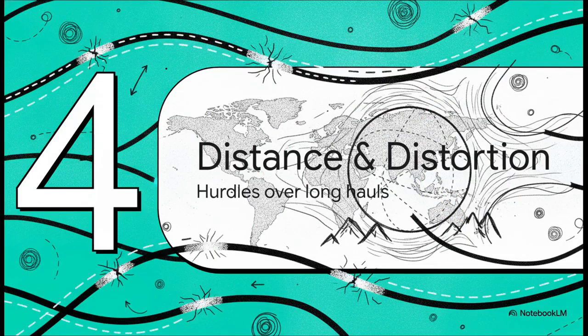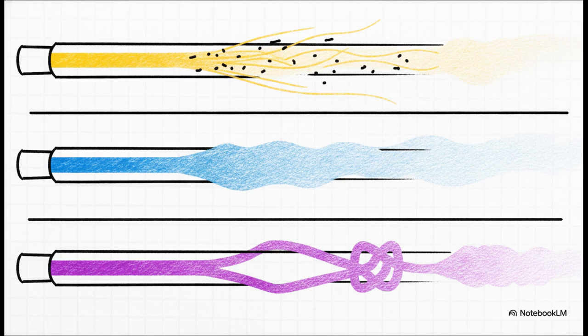Section 4, overcoming distance and distortion, hurdles over long hauls. So, over massive continent-spanning distances, light does face 3 major hurdles. First up is attenuation. That's just your basic signal loss caused by microscopic impurities or scattering. Second is dispersion. See, because different light rays can take slightly different amounts of time to travel through the fiber, your crisp digital pulse can actually broaden and smear out over time, which really bottlenecks your bandwidth.